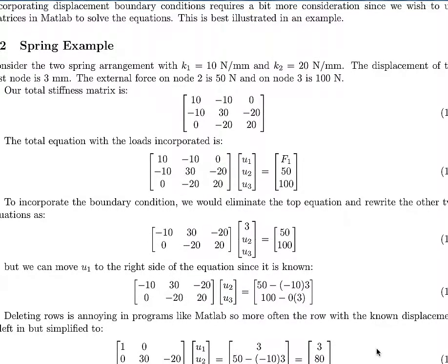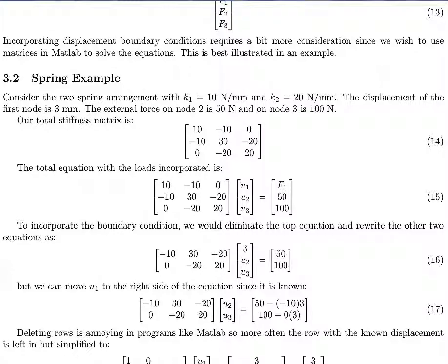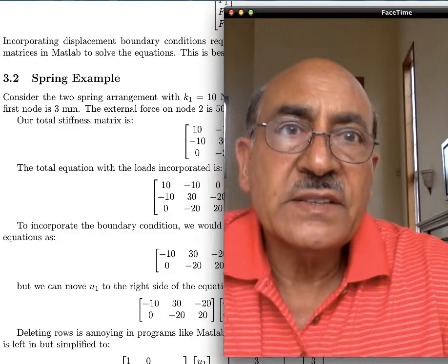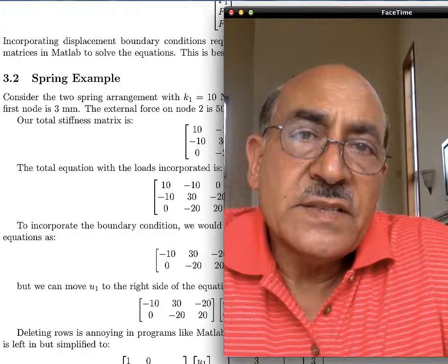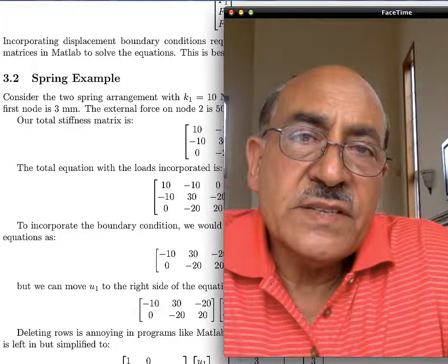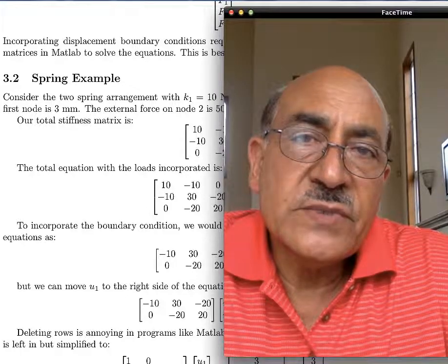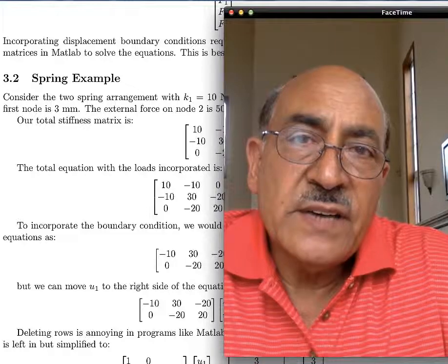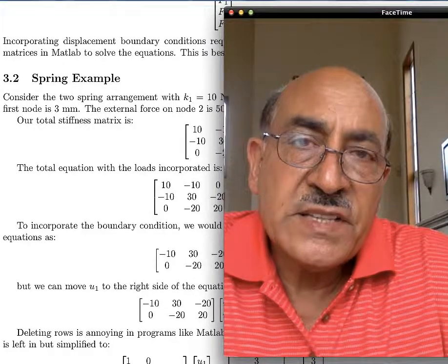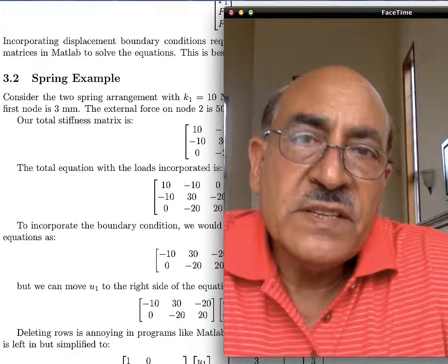The spring example will illustrate what's needed with the boundary condition. What I found interesting about this procedure is that I can now set up the system, because I have a number of nodes connected with springs, and each spring has a very simple 2 by 2 stiffness matrix, multiplied by the displacements, giving me the internal forces.